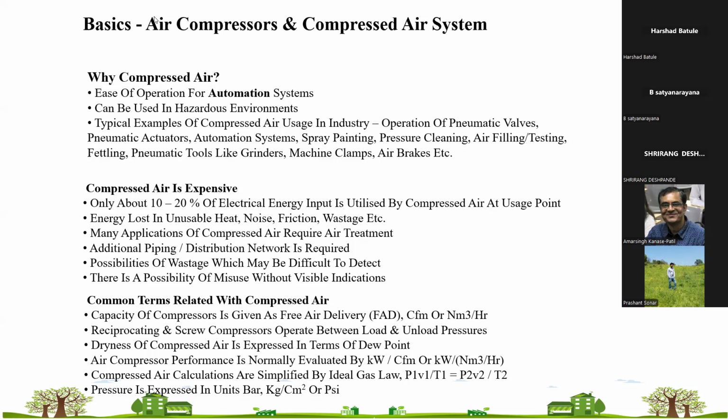When we are dealing with an air compressor or compressed air system, there are multiple terms used. If we are reviewing the nameplate of any air compressor, there will be the model of the air compressor, whichever make or model it is. Then there will be free air delivery, majorly in CFM or liters per second.